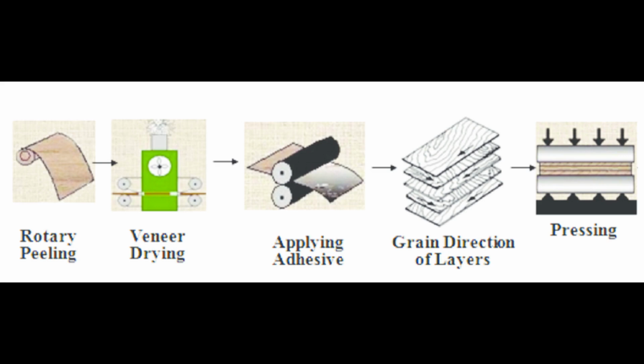Aircraft plywood is available in thickness of 1/8 inch and upwards. Typically, aircraft plywood uses veneers of 0.5 mm thickness, although much thinner veneers such as 0.1 mm are also used in construction of some of the thinner panels.